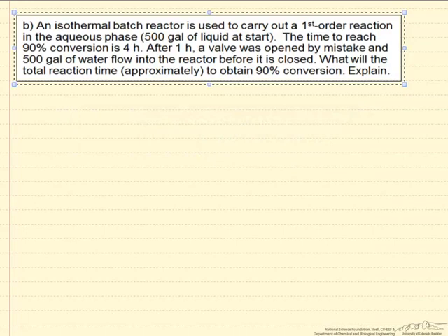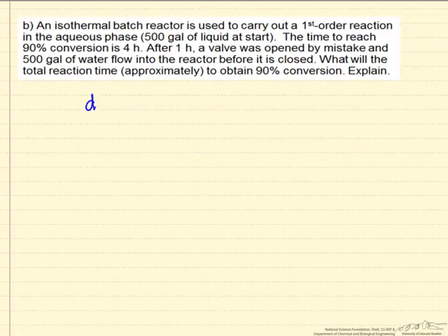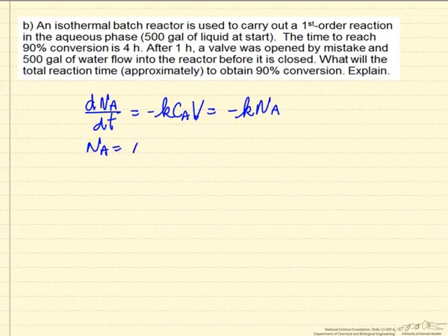This is a first order reaction. If we were to look at the mass balance for a first order reaction, batch reactor, we can see it only depends on the number of moles. Because it only depends on the number of moles, we can certainly solve this: the number of moles at any given time is the starting number of moles times an exponential in time.